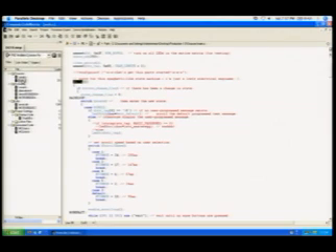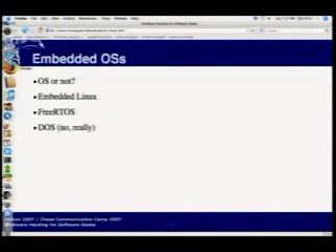The downside of not having an operating system is, of course, that you have to do all the hardware access yourself. However, if the processor is simple enough that you can't put an OS on it, there's not going to be a lot of hardware to be accessing. It's generally the AVR chips that I'm most familiar with. Doing SPI communications is a simple matter of setting a few registers, then loading one variable with what you want sent out the SPI port, and then checking a few milliseconds later to see what came back in.